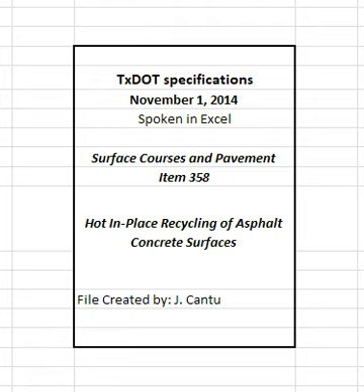3.1.4 Mixing Unit. Provide equipment with an onboard mixing chamber that is capable of thoroughly mixing the heated, reworked material with new materials. Enclose and configure the mixing chamber such that no milled material escapes or bypasses the mixer chamber. Ensure that the rotation of the mixer apparatus does not cause segregation during the mixing process.